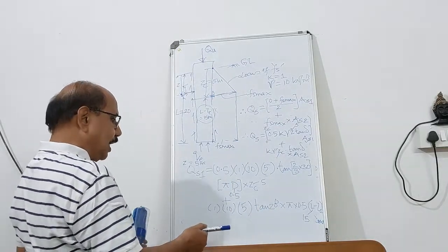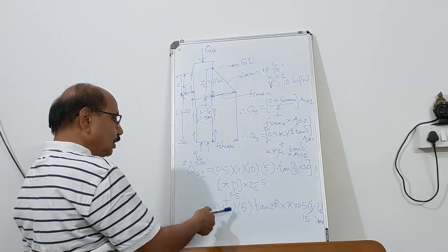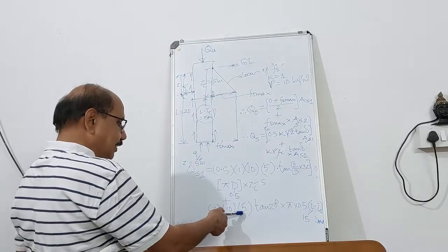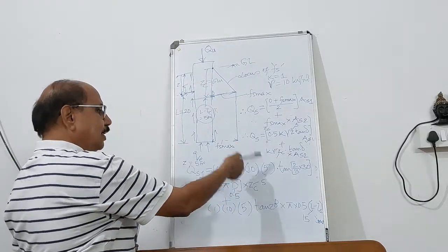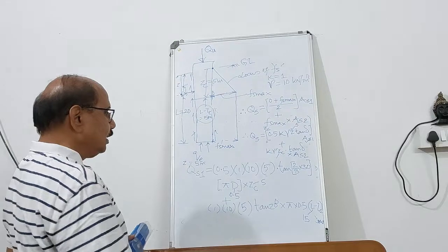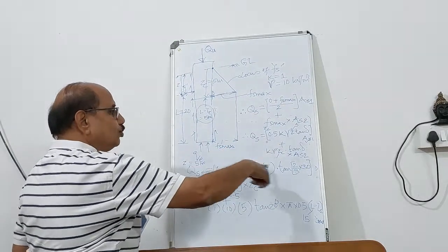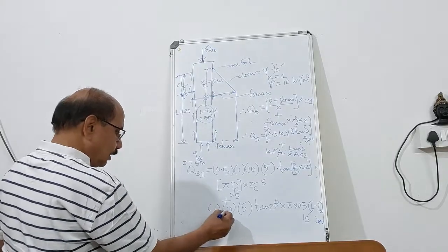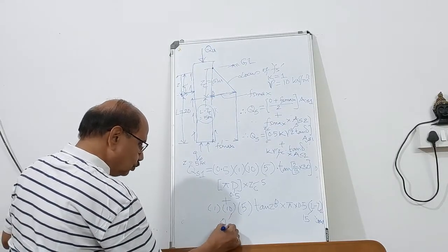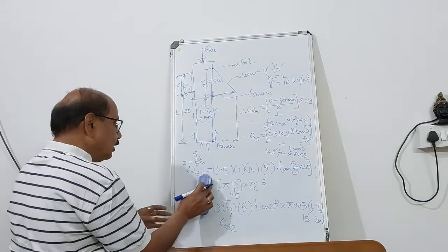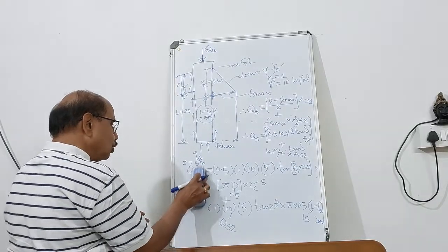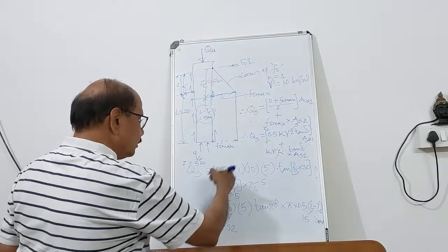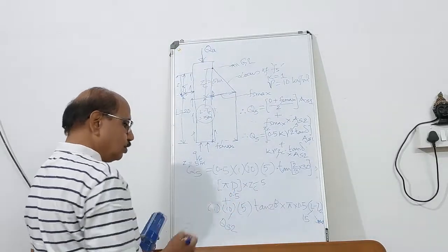And Fs max is going to be at Z critical, here 5, here up to Z critical 5. So this formula is to be used for computing QS1 and this becomes QS2. So the total, if you add up, this becomes QS. So total skin friction equals QS1 plus QS2.